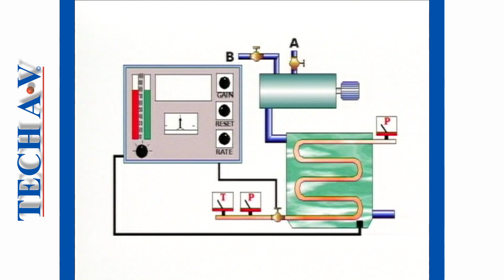Pressure and temperature meters were installed in the steam supply line, and a pressure meter in the heat exchanger shell. The measurements revealed that the demand for steam in other areas of the plant affected the pressure and temperature of the steam supply to the heat exchanger. When the steam pressure rose, the steam temperature rose, and conversely, when the pressure fell, the temperature fell. These variations were also apparent in the heat exchanger shell.